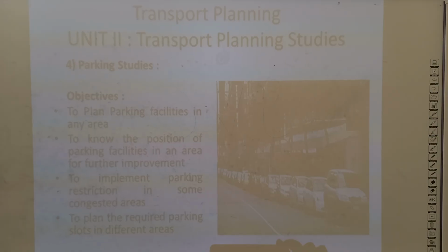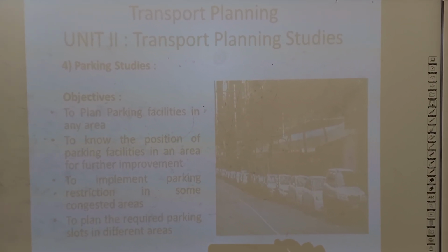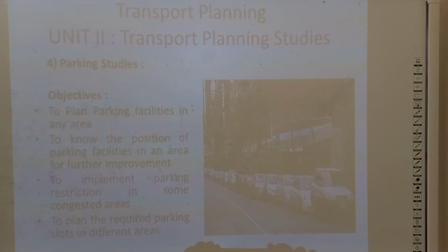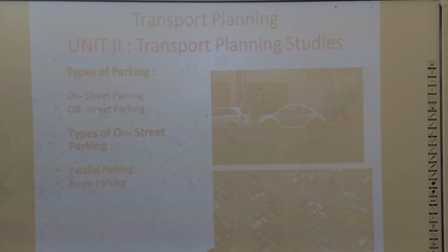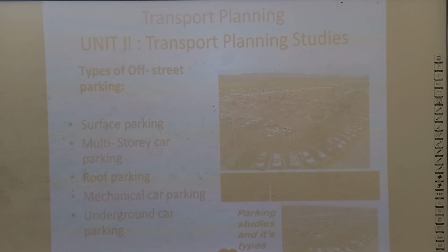Coming to the parking studies, I will give a brief idea. Parking is very important because if the vehicles are not parked properly, a lot of space is occupied by illegal parking. Hence we have to go for either on-street parking or off-street parking as per the space available on the road, and accordingly we can evaluate the parking parameters. A lot of parking parameters are there so that we can evaluate the parking fees, and based on that we can control the vehicles parking.